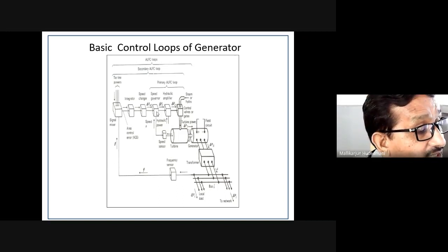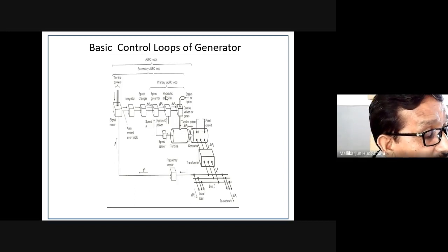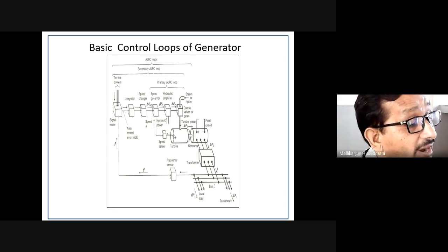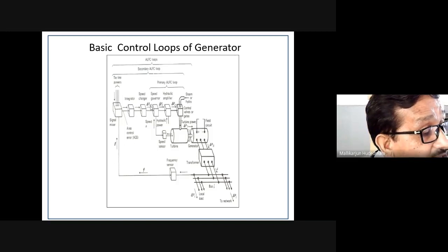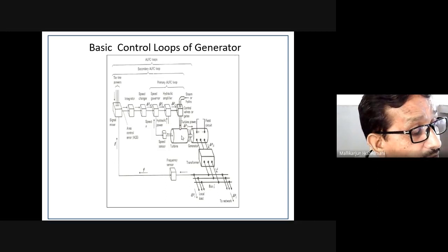The speed governor in turn acts individually up to that point. If it is able to achieve it, well done. If it is stalling there, not able to achieve it, then there is a need for secondary control to supervise and change the set point, such that relaxation is given to this controller to increase the input further to the turbine.